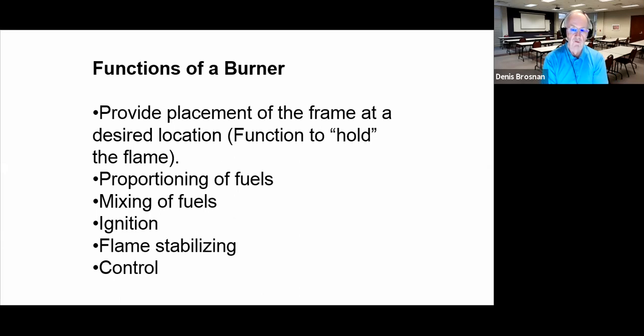Each burner that's manufactured by a company like Honeywell Hauck is going to have certain operating parameters, and there's going to be a bulletin for each burner type, each particular model, that explains the minimum pressure, the maximum pressure, and the airflow rates to maintain a stable flame. If you don't, then you'll have a flame out situation. So the purpose of the plumbing section is to provide air at the flow rates that are required to make the burner do its job.